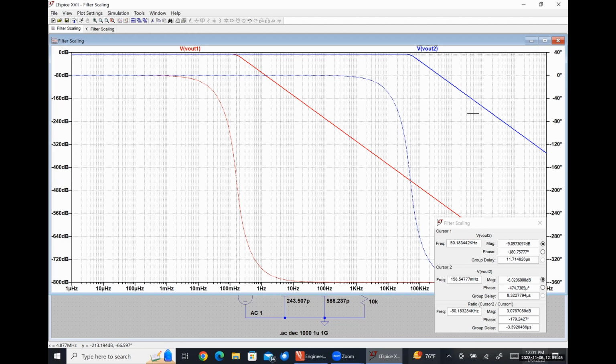So it's done exactly what we needed it to do. It replicated our frequency response entirely, both the magnitude and the phase. We simply shifted our cutoff frequency from 1 radian per second to 100 pi kiloradians per second. Everything else is literally identical.